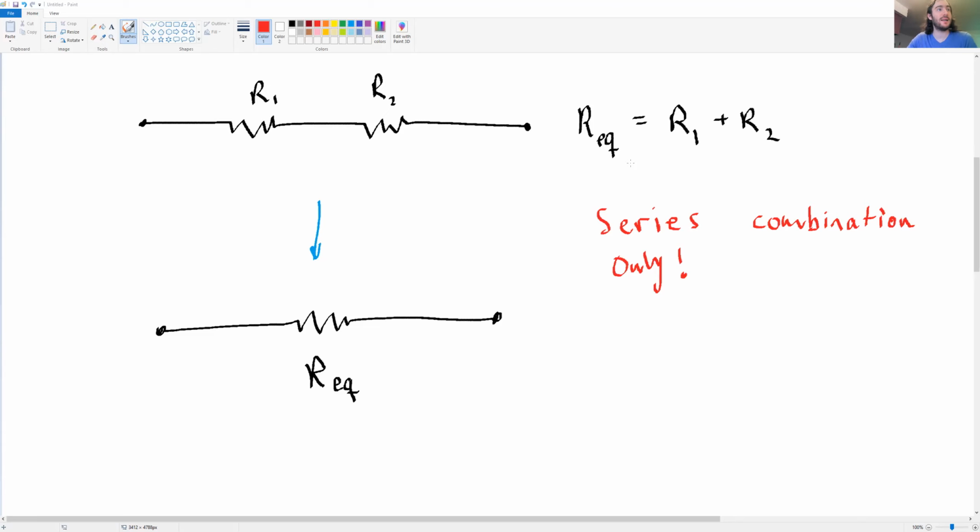Remember, I gave you guys an exercise where we looked at the case when the resistance values for resistors in parallel were the same value, and you see that the equivalent resistance is 1/3 of the value of one of those resistors. So use tricks like that to recognize quick combinations to save yourself time.